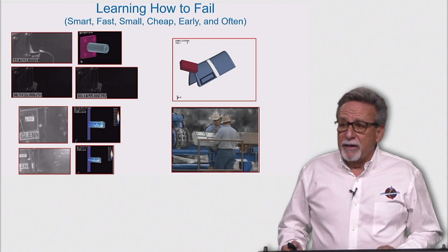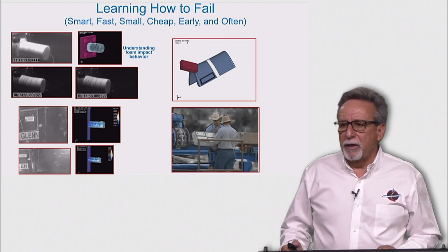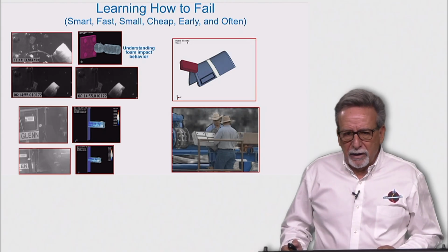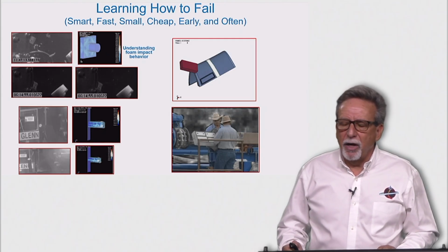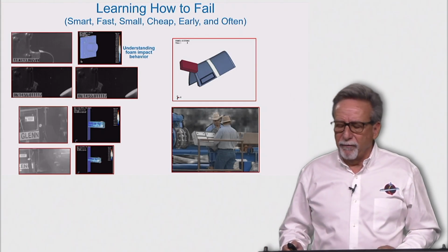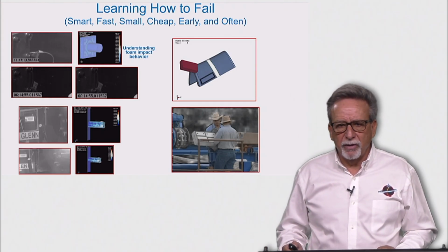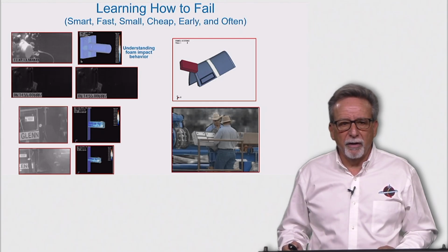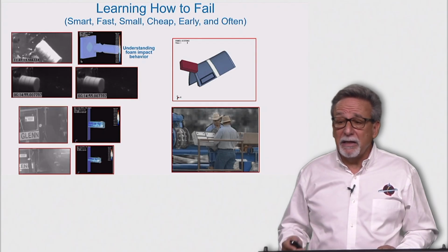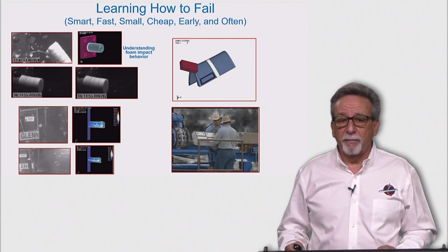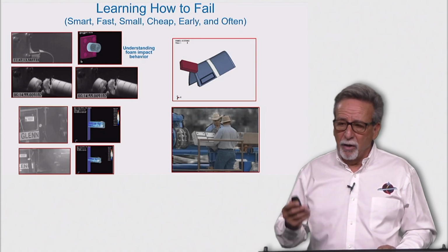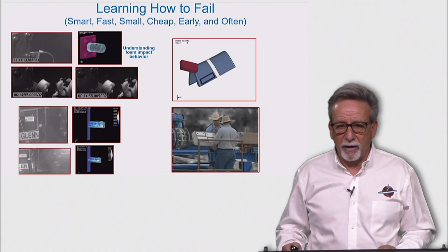Now I will show you the difference when you conduct an intelligent fast failure using a building block approach. The folks at Glenn Research Center conducted a number of tests using small foam samples and impacting on a load cell, as you see here in the upper left figure. We approached these tests as the means to get as much knowledge as possible about the damage from foam debris to an RCC leading edge by these simple, inexpensive tests.